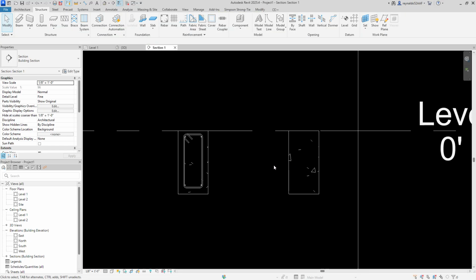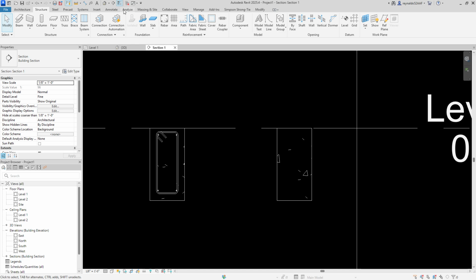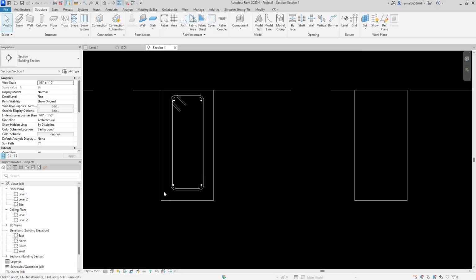What you need to do is go to your rebar, go to structural, go to your covers, and quickly set those on the concrete beam you want to have the rebar copied to. So quickly, since you already have the settings preset, you can just do that, and then click the bottom, do that, and then we'll do the top, and we'll make that 1.5 inches. Now that that's done, we'll click escape. Now we can go back in here.